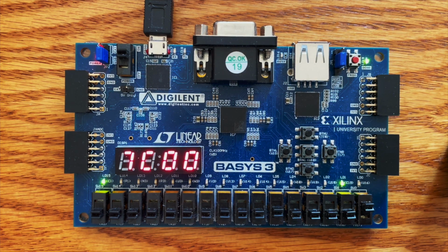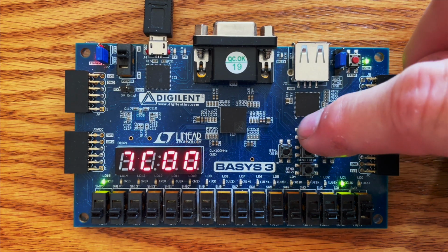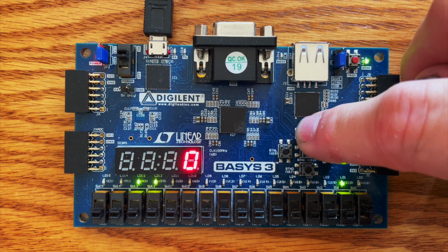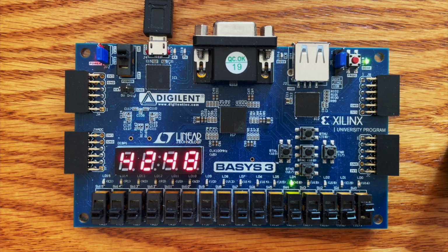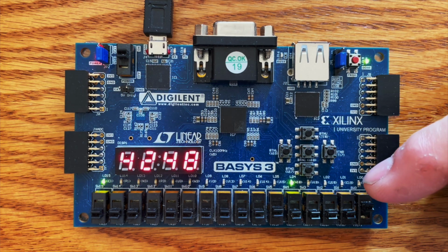You can verify that the register values have been restored by pressing the upper push button until LED 13, the start signal, lights. If the board was successfully reset, the final value shown in the 7-segment display will be 4248 hexadecimal. When the division computation is completed, there may be one or more exceptions which have occurred.